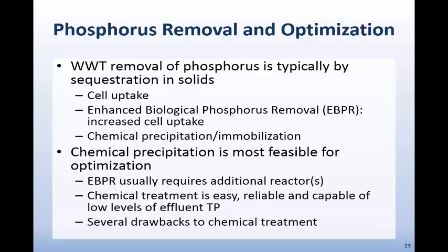And frankly, most of the case studies where they were focused on low-cost phosphorus removal and the plant was not designed for phosphorus removal, most commonly we saw chemical precipitation used. Chemical precipitation is very well documented in guidance manuals and so forth, so we didn't really focus on it in the case studies.